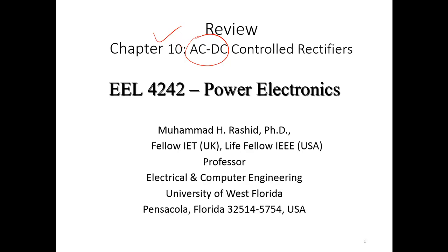But controlled rectifiers use thyristors, whereby one can control the conduction time of the thyristors and control the output voltage. This type of controller is used for variable DC output voltage, wherever you need variable DC output voltage, like driving DC motors or charging a battery, or any other application where you need a variable DC from a fixed supply. They are used for large power applications, like heating, welding, or DC supply, where you need a large variable DC voltage from a fixed AC voltage.